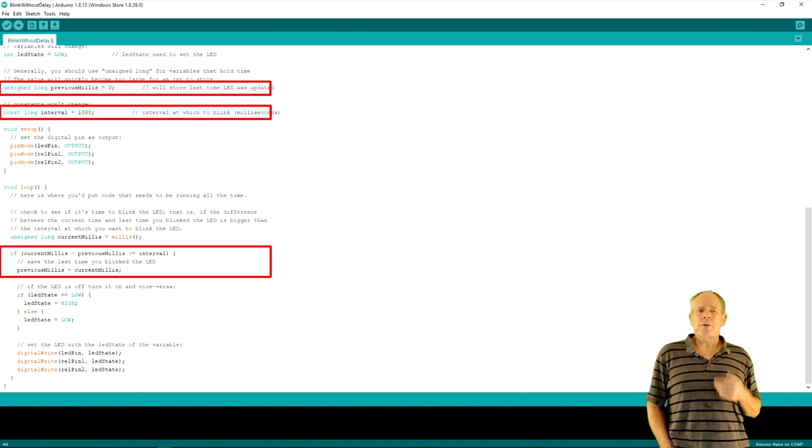I did not measure it, but on a Nano we should loop around 30,000 times for every relay activation, which basically is processor capacity that can be used for other things. If we would use a delay function between the relay activations, the processor would just be sitting there doing nothing. Not a problem in this case, but if you have other stuff to do, you would lose valuable performance. Therefore, if you are a less experienced programmer, I recommend to study this simple principle of avoiding delay functions, as you will use it over and over again.